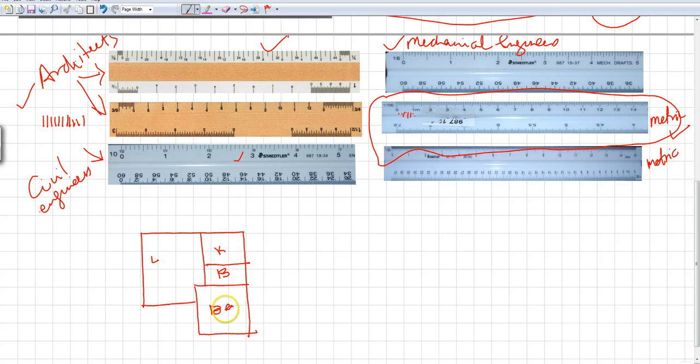Okay, now we are going to measure the distances, which is all the way from here to here. Then measure this distance, and measure this distance using what? Using the architect scale. Now let's see, how do we read the architect scale? Now architect scale has all these numbers that define the scale of the drawing.